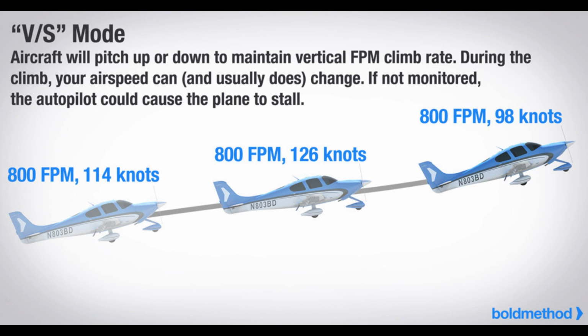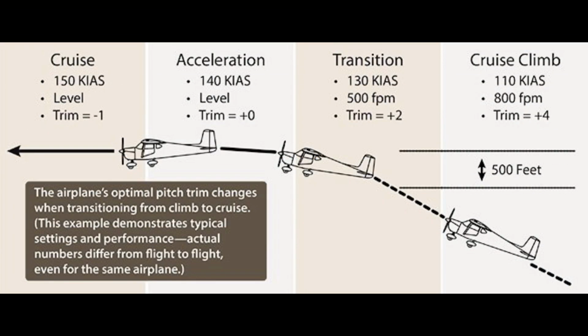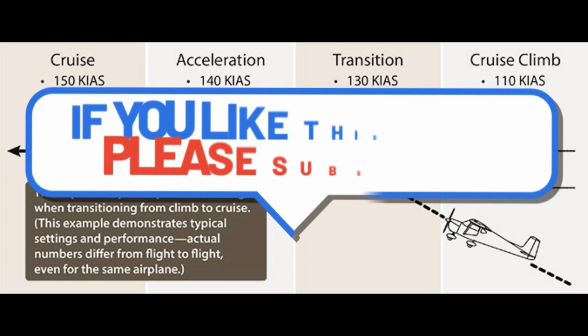4. Determine the available methods of activating the altitude armed or capture mode. 5. Determine the average power necessary for normal climbs and descents. Practice changing the power to these settings in coordination with making the FD/autopilot mode changes.